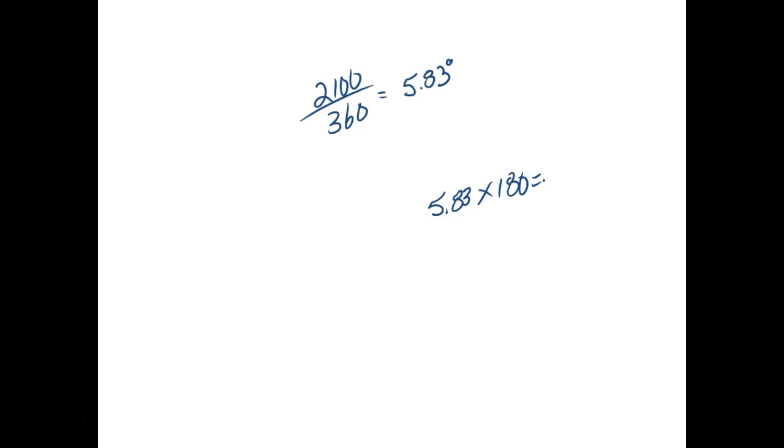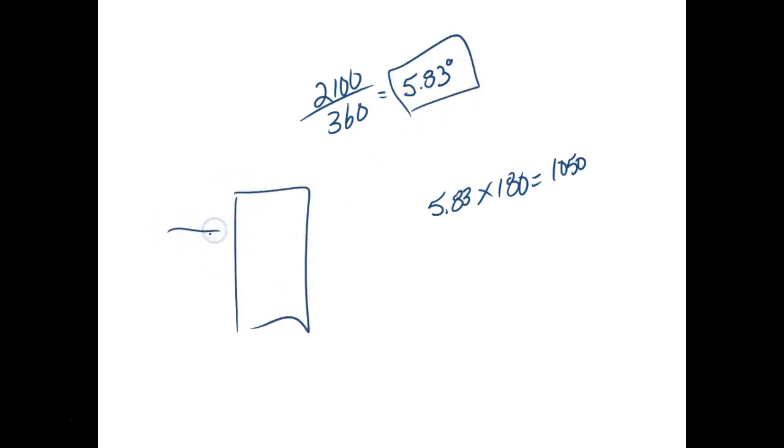Yeah, which is half of 2100. So what I can do now, once I've got this, we call it a transfer function. Once I've got that, now I can relate what? And what I could do is take this and just put it in a multiply instruction. So I could take my count, you understand, multiply it by that, and let it do the math for me, right? Make sense? And then compare it when it gets up to a certain value.